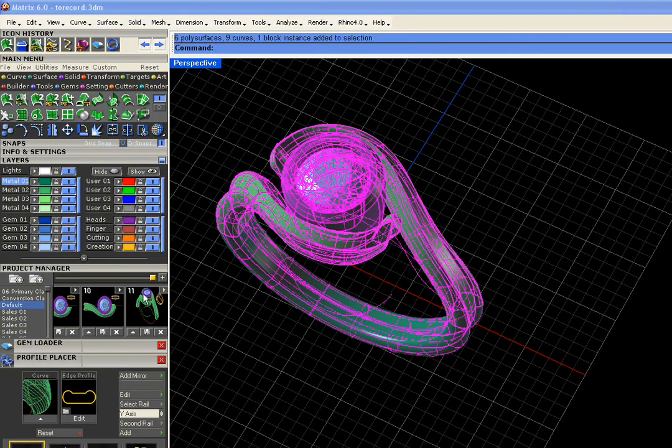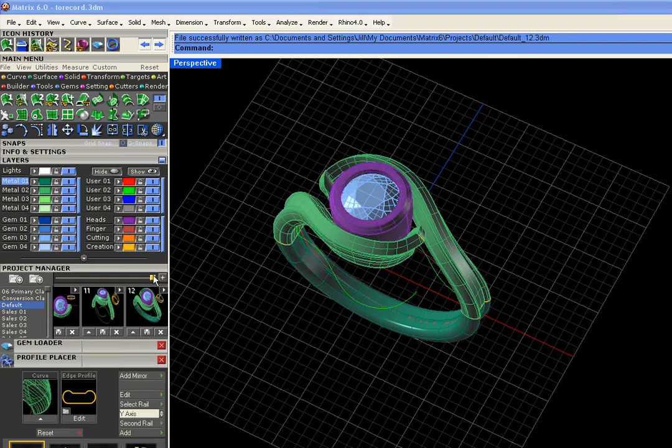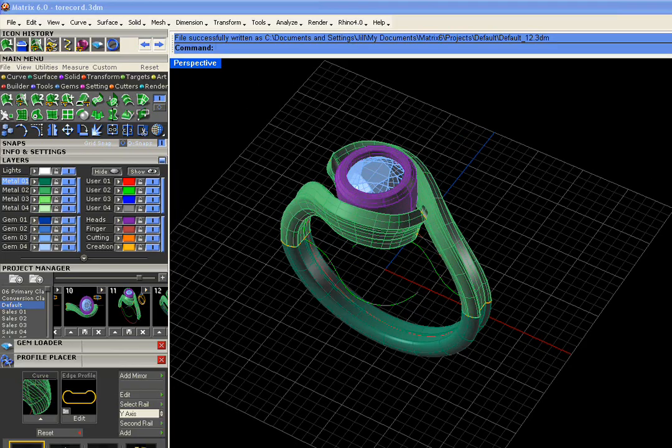Job bag this for safekeeping. And when you want to change this ring, you'll need to start from this version right here, which is why we job bag all the way along. Then just complete the rotation and the sweep last of all. So you've really got a history-enabled ring. Then you've just got two steps left to finish it off.